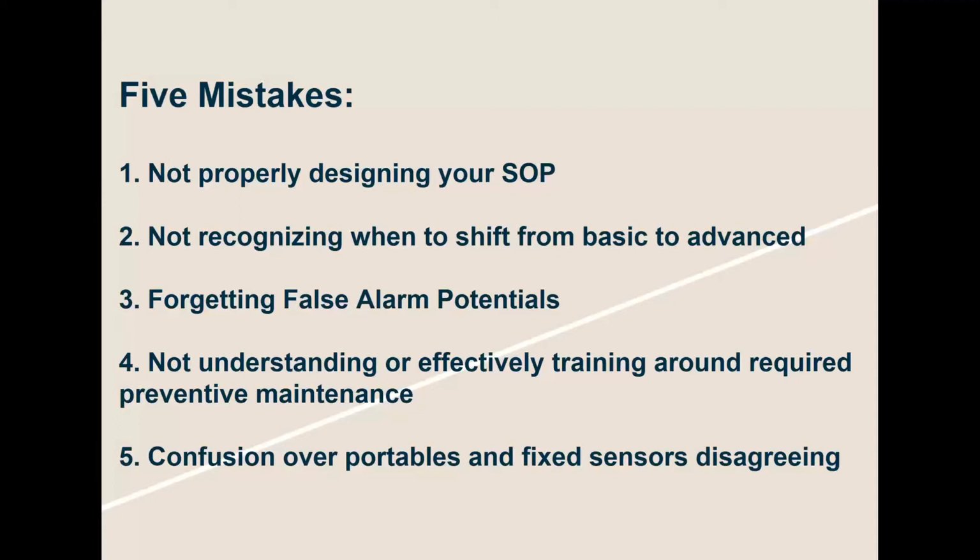There are so many things that once you do the installation creates false alarms that if people just did a little bit of design work up front that took some of those things into account, they may be able to not have to deal with some of those. So we'll talk through those. Not understanding some of the preventive maintenance to do. And we've certainly seen where people put a system in and they ignore it, or they don't do it right, or they'll get the cheapest way that they can to upkeep it and forget some critical things, and so the system doesn't work right. So we want to try to talk through some of that.